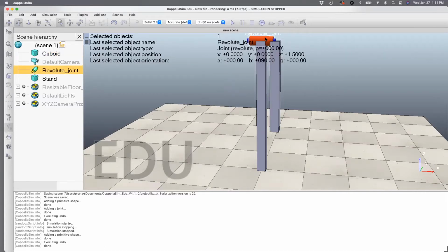Now maybe we don't like the pendulum joint to be like this. Maybe we want to move the joint slightly to the right, so that part of it is covered, just so it looks aesthetically pleasing. When you do the simulation, the simulator does not care where the joint is relative to the location. It's not a physical system, it's only the way it's defined here. So if you want to make it look nice, it's fine, but if you don't care, this should also work the same way it would if you had not moved the joint.